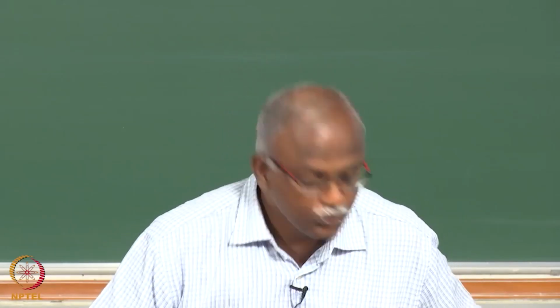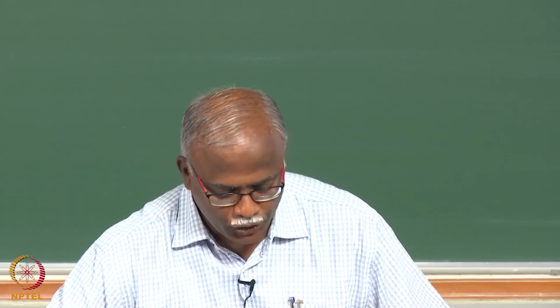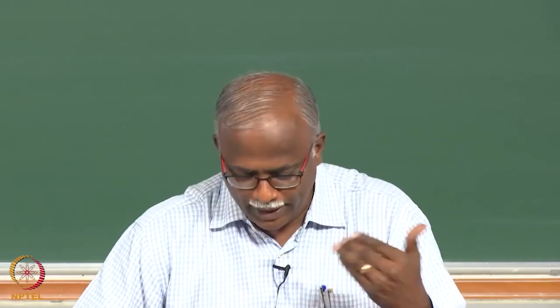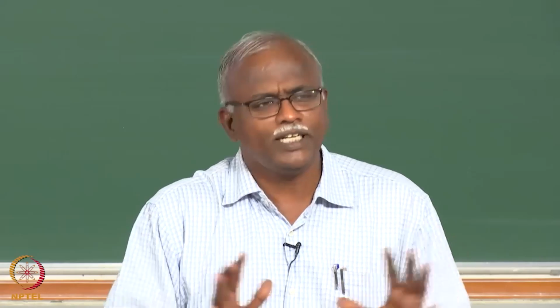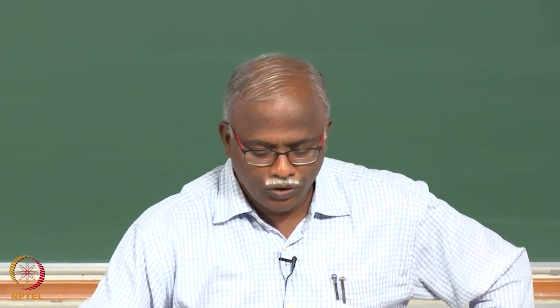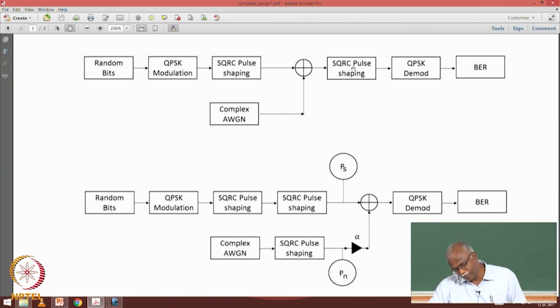Okay, what I want to do in the couple of minutes that are remaining is to show you the computer assignment and encourage you to start thinking about it. The TAs and I will be happy to help you. Basically the goal is to verify the theoretical bit error rate performance of a QPSK system. The way you would do it in a conventional sense is you would generate bits, modulate them using QPSK, add some pulse shaping, noise, and then pass it through a matched filter, demod, and then compute the bit error rate. That's what is supposed to be done.